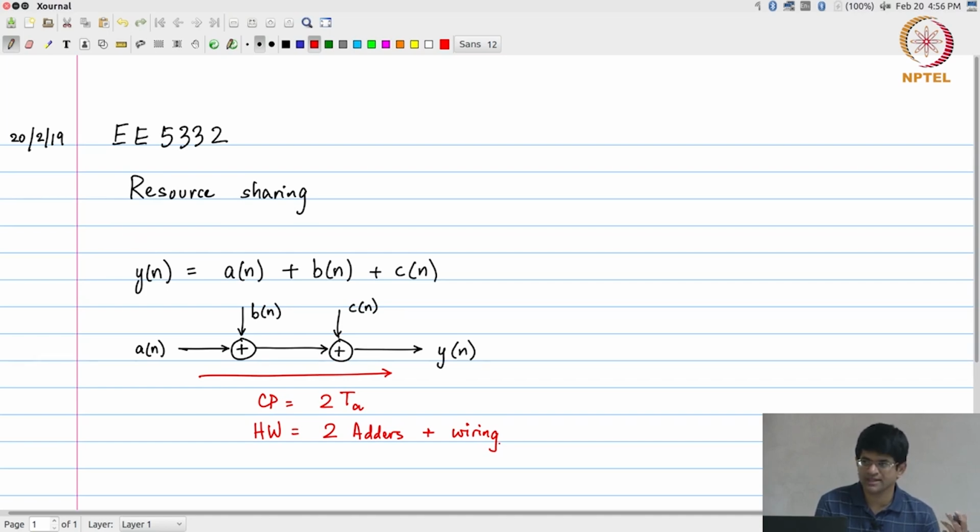In modern ASIC design we have now reached a stage where the interconnect, the wires that connect different hardware modules together, occupies a very significant amount of space and accounts for a very significant part of the total delay through the circuit. We are in fact hitting cases where the total speed at which a system can operate is not limited by how fast the individual gates can operate, but by how slow the wiring between them is.